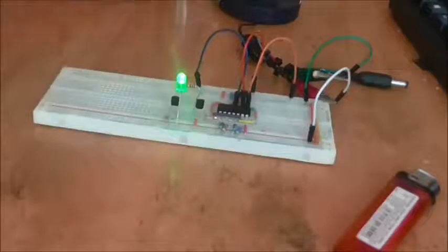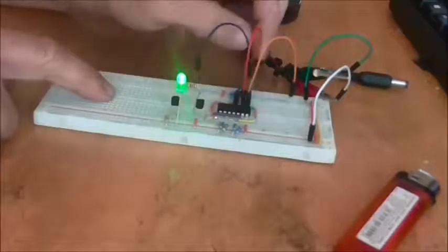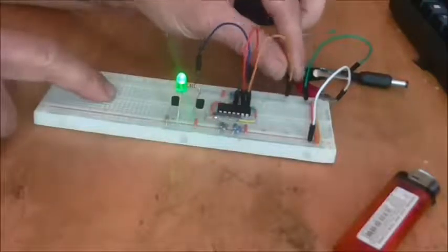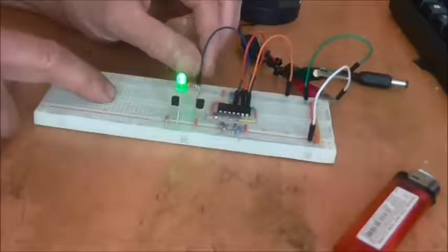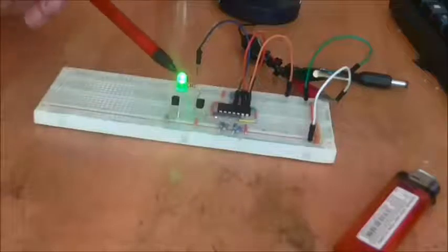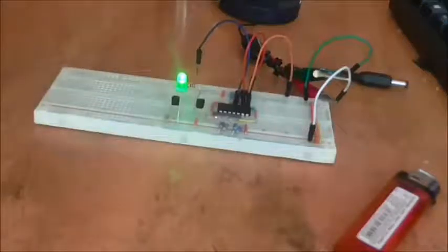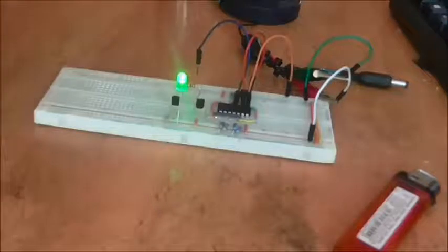Now, if I take input C out again, and even input B, and input A, and I do what I like with them, wiggle them about as much as I want, it doesn't go off. And that's what the thyristor is doing. It's keeping the alarm, or the visual indicator of the alarm in the shape of the LED in this case, in a stable condition of being high, even though the gate may well have gone low or high.